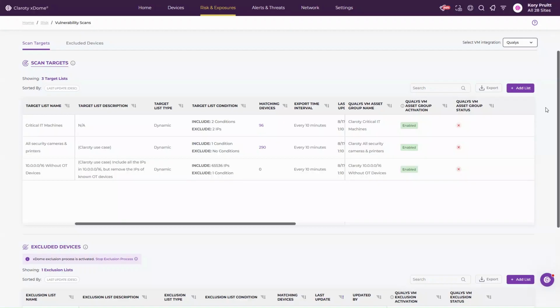Another area where working with IT and OT security teams can be challenging is around the use of vulnerability scanners. Most organizations will already have a traditional IT vulnerability scanning tool in place. Unfortunately, in most situations, the vulnerability scanners are not suitable for use within OT environments due to the very real risk of process disruption. While there are traditional IT assets that exist within these environments, the assets are often intermixed with the more sensitive OT assets, which makes it difficult to effectively identify which assets can be safely scanned and which cannot.